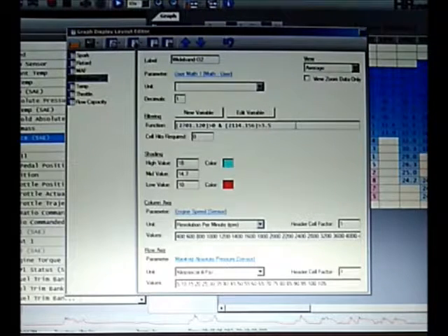Normally when you are recording air fuel data, you want it to be during a phase of acceleration, or something that involves you actively putting power into the car. If you're decelerating, your foot's off the gas pedal and the car is slowing down, that's contaminated data that's going to screw up your calculations. And most of the time, I would say most users are not considering that. Most users are probably allowing that data to mix with the rest of their scan, and it's contaminating their results.